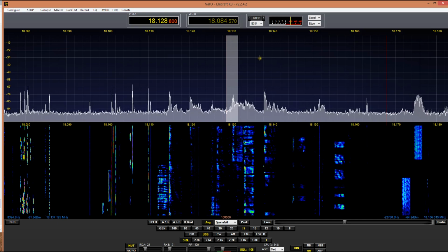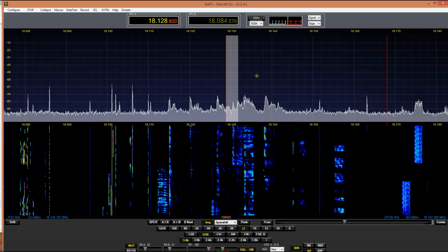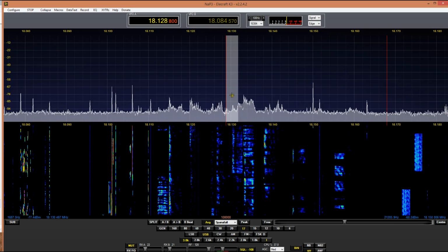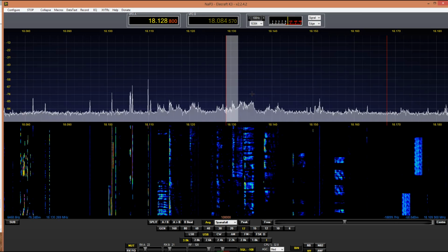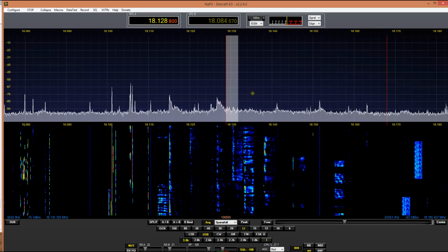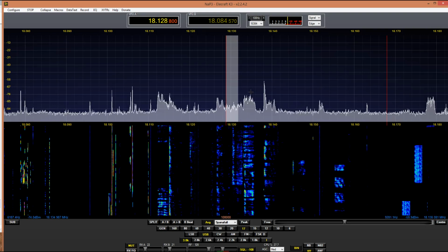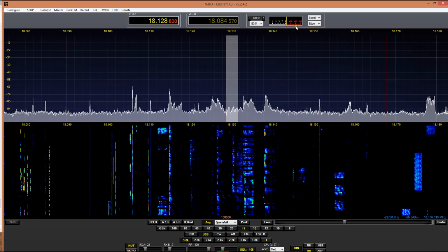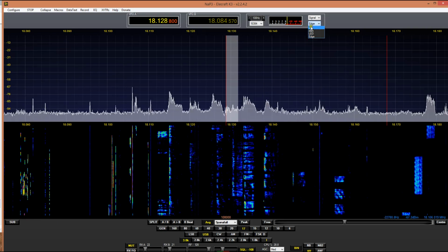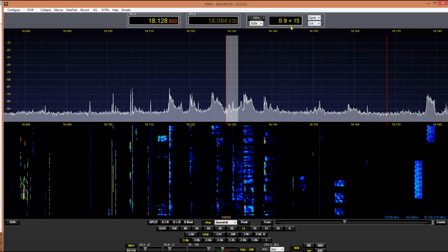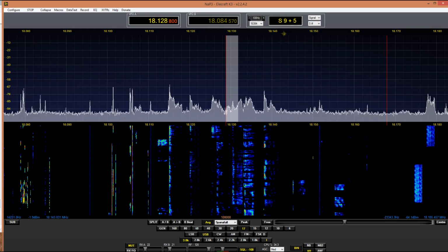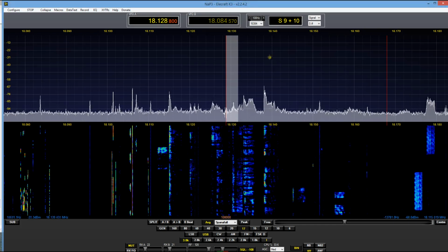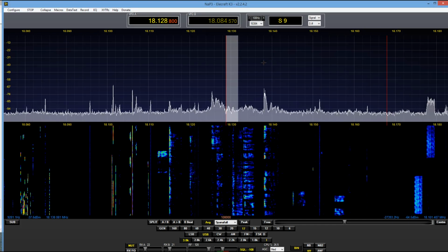So NaP3, in lieu of that, is trying to figure out what's the S-meter reading from the pan adapter, and it doesn't do a very good job of that. However, a subsequent firmware revision for the KX3 will make the S-meter reading available, and you'll be able to see accurate S-meter readings up here. K3, by the way, does make that available. So that's one advantage the K3 would have.